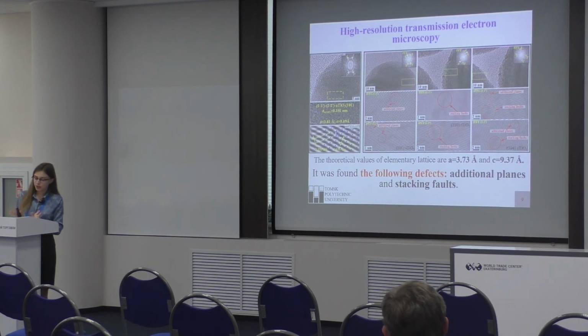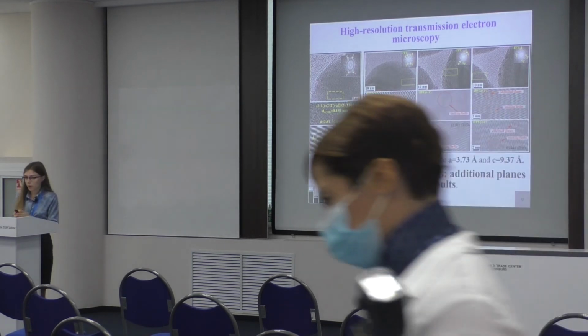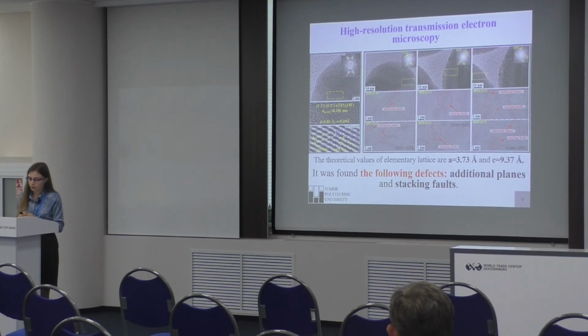However, such an ordered structure is not found in all anatase particles. In the slide, images with a set of crystal planes of various directions of anatase and rutile are presented to show a highly disrupted or disordered crystal structure. In most cases, the formation of a defect structure is observed. The appearance of such dislocations is usually caused by mechanical shear stresses, which in this case are the result of shock waves arising in the plasma dynamic synthesis process.